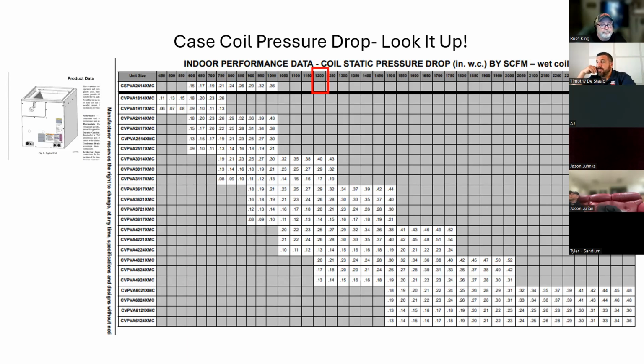Let's say instead of that heat pump, we got a furnace and we're trying to move 1200 CFMs, and we got 3 coils to choose from. Which coil is the one that we're going to want to choose? Well, we may have to go back to Manual S to make sure it's going to work, but I'm going to choose that bottom one that's only going to give me a 0.14 pressure drop. Because if I choose the 3617 coil, I've got almost 0.3 inches of pressure drop. I started out with 0.5. There's no way that's going to work.